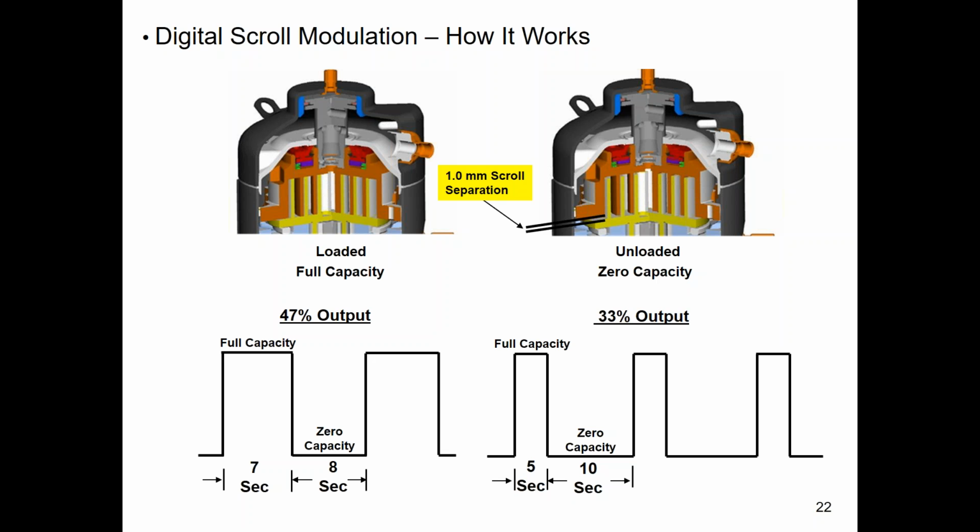And the liquid line's already obviously solid liquid, but your suction line needs to be vapor. We fill that suction line up with liquid, and now we start the condensing unit up, start the compressor up, and we draw all that liquid back, and it washes the oil off the bearings in the compressor, doing damage. And even worse yet, you can slug it and start breaking pistons, breaking scroll flanks, just destroying the compressor. So that's what it is. It's all about off-cycle refrigerant migration.